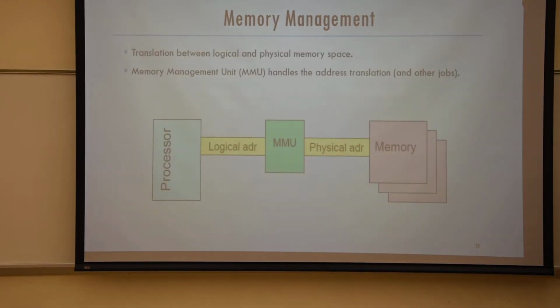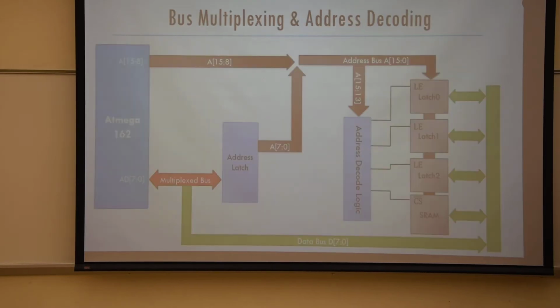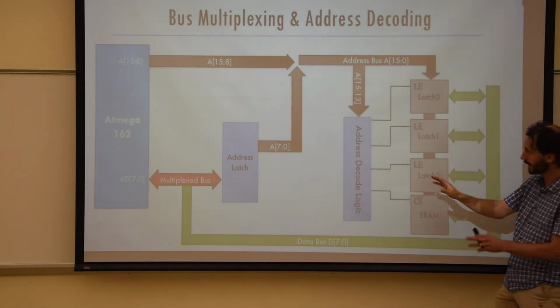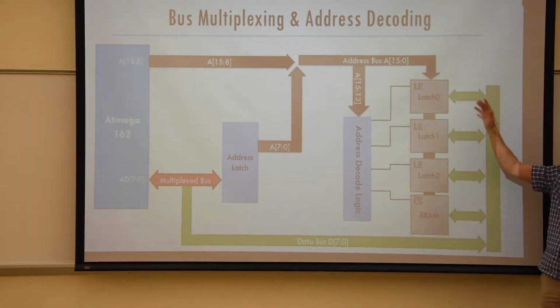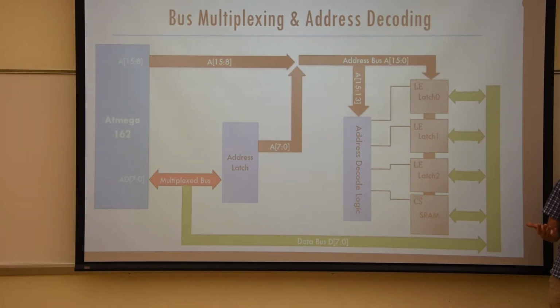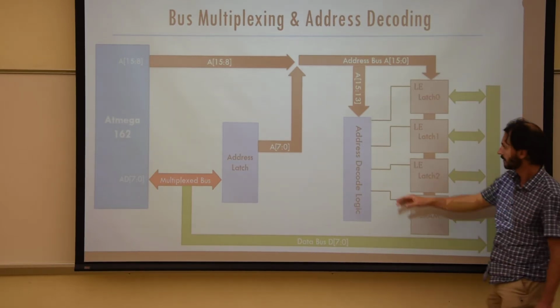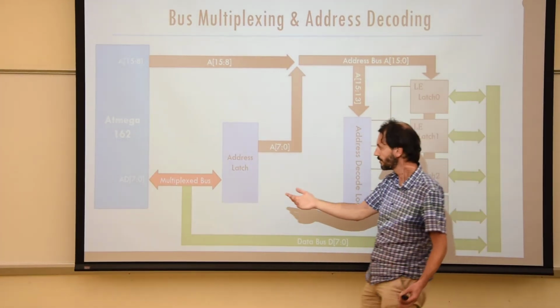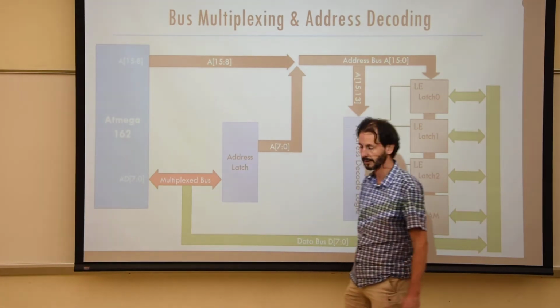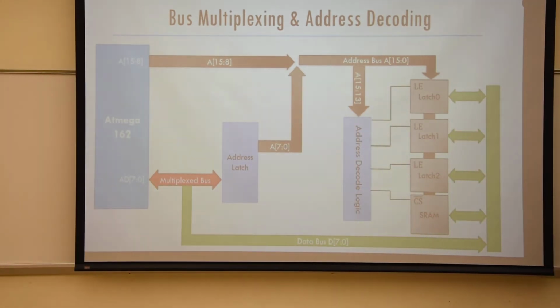So this is a way to connect the processor not just to memory, but also to other peripherals that can be considered as addressable objects. So use addresses for that as well. You have some specific address decoder logic for this configuration, and you have the usual multiplexing of data and address lines. So I hope that you really understand this, and there is in the advanced problem set a question about this, a different configuration. You would do the same thing.